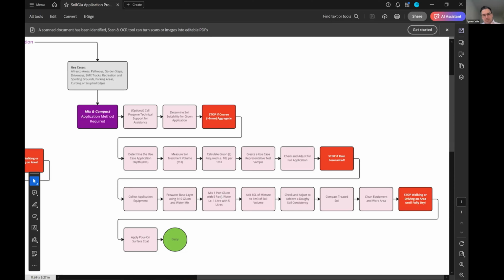Just sort of smear out the soil, and then I'm pouring on. I'm using the pouring on method on top of that inch thick soil, and then I rake it in. So I mix it with a rake, and then I repeat. I just repeat that over and over again until I get it up to the height that I want it to be, and that's why I'm calling it the lasagna method.